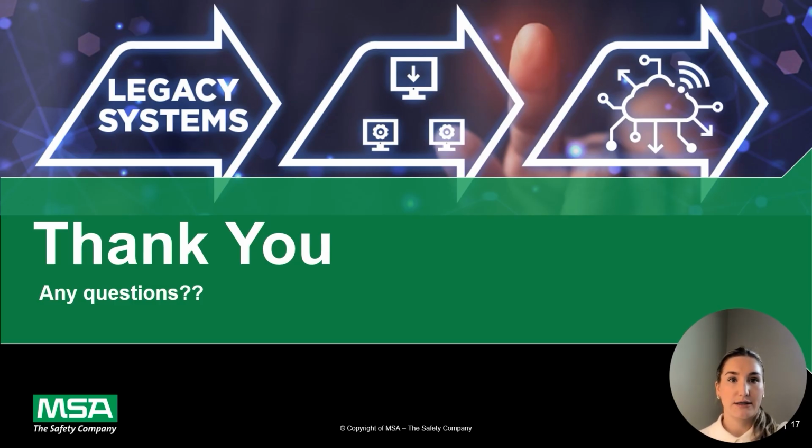All right. I see another question: how does latency affect Modbus and IoT systems? Great question, because latency is often overlooked until it becomes a big problem. The truth is that Modbus, as we know, was not built for high-speed real-time applications. It's perfectly fine for equipment monitoring, but it's just not ideal for high-frequency motion control or very fast safety interlocks.